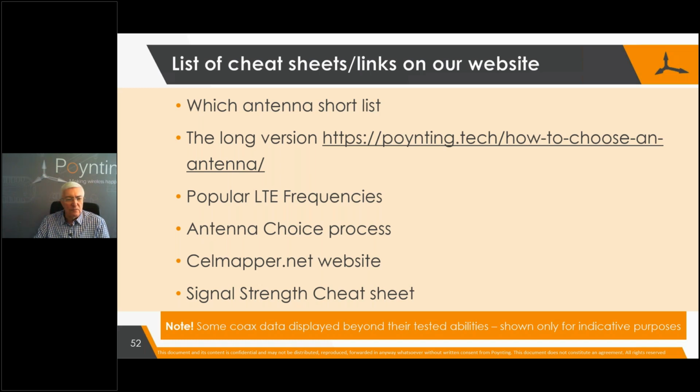And then very briefly, certainly not last but least, we are busy developing an antenna that has the ability to take the router in the back. Like you saw with the attenuation of long RF leads, that will shorten the RF leads to a few centimeters or a few inches inside the housing at the back of the antenna, making full use of the excellent capabilities of our OMNI and our directional antennas.